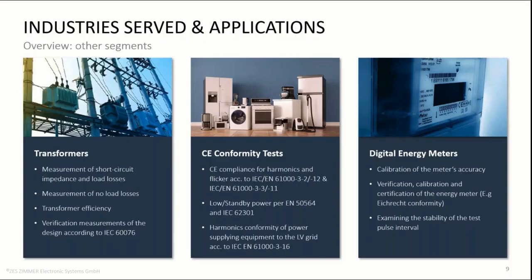Similar laws most likely apply in Italy and most other countries, and there precision power analyzers are being used in the development, verification, and calibration stages of such devices to ensure their accuracy and compliance. Moreover, since these energy meters use repeating pulses to indicate the consumed energy, a power analyzer being able to analyze these pulses can serve in examining their stability and consistency.